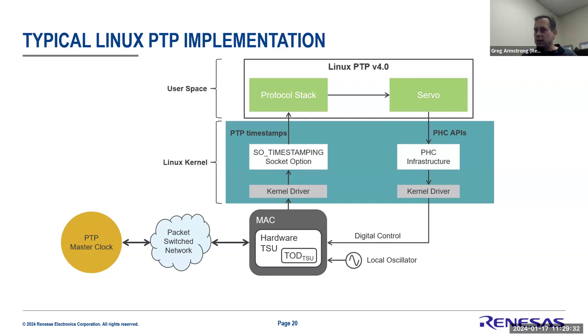But it itself, there's a little servo in there. Someone wrote a simple little PI filter and even an example of using a weighted mechanism of filtering and says, hey, well, I can filter this clock offset that's being sent to me and resynthesize the clock to try to eliminate the drift component and try to maintain that traceability to the grandmaster clock. But again, a lot of people wouldn't know how to configure it, use it, or even be able to understand it if they try to read that code.